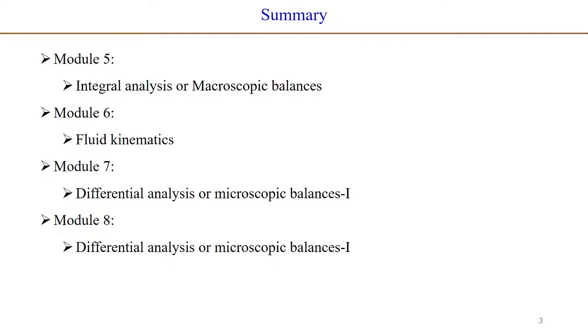What we solved is the combination of the two, and because we assume that the flow is fully developed, we could neglect the nonlinear term there, u du by dx, or the v dot del v term. So when that term could be neglected, assuming the fully developed flow, we could combine both the solutions, and we saw that it is a combination of linear and parabolic velocity profile when both the upper plate is moving and there is a pressure gradient to drive the flow.